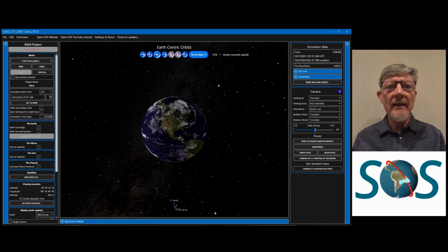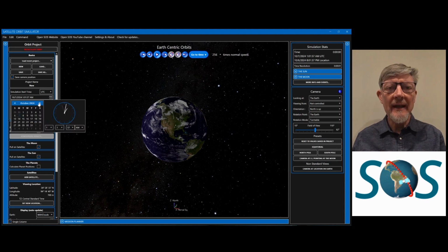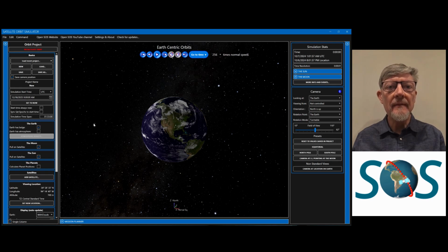Then set the simulation start time to December 18th, 2025 at 9 a.m. I'll wait while you type that in. OK, click outside the Date Time tool to close it. Next, check the Synchronize Epoch to Start Time checkbox.